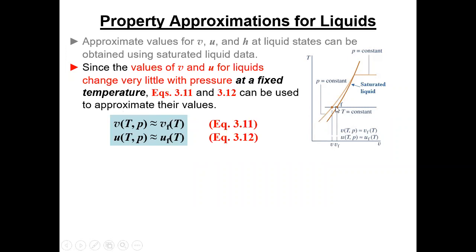which can be pretty handy because what you're going to find is when you go to the compressed liquid tables, that first pressure might be 500 psi or 1,000. And the reason for that is the numbers don't change very much for a given temperature until the pressures get tremendously high. And so, you're not going to put a listing in a table that's like 0.1% change from the saturated number. So you've got to get that far away in terms of pressure before you get enough of an increase that it's worth putting in the table. So when they build the tables, that's what they do.